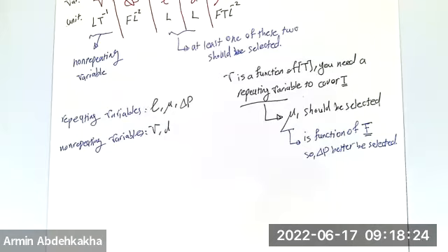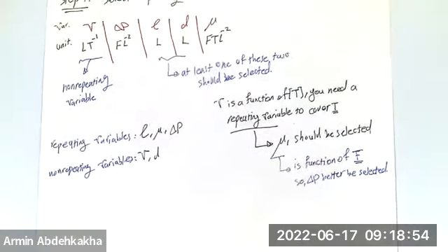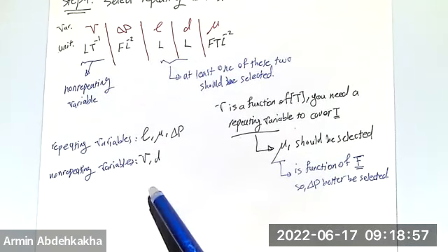But we are not talking about just exams. We are talking about your research in the future, or the work that you have in a company when you have a new problem. Then what is your job in finding those pi terms? The reason for doing that is finding the pi terms that at least are known. You remember that we talked about different pi terms like the Reynolds number? If that combination gives you the Reynolds number, for example, here, if you had rho V D over mu, you have all terms needed for the Reynolds number, okay?